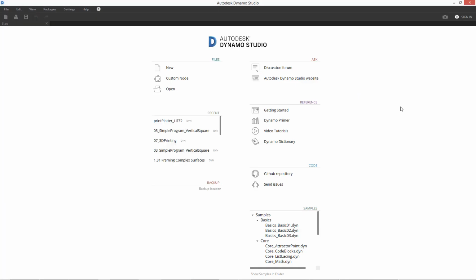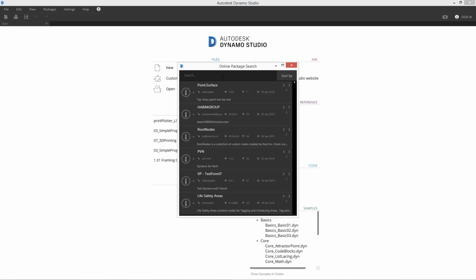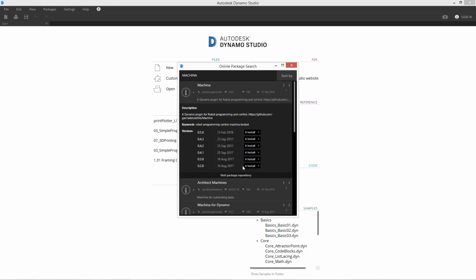Something else that you may want to try is using Machina in Dynamo BIM. The API, the interface, and the logic are exactly the same as they are in Grasshopper, and also the same as in the core library, the C# library that runs behind these visual programming languages. The way to install Machina for Dynamo is by going to the package manager, going to packages, and searching for the package you want to install. If you type Machina, you should see a drop-down of all the different versions that have been published. You should always try to install the latest version.